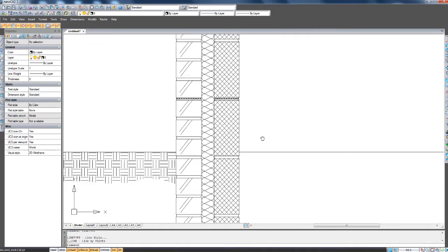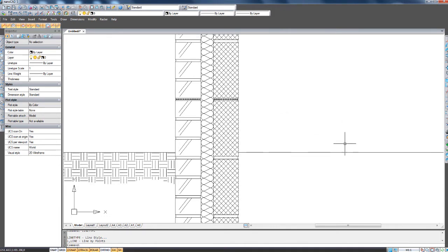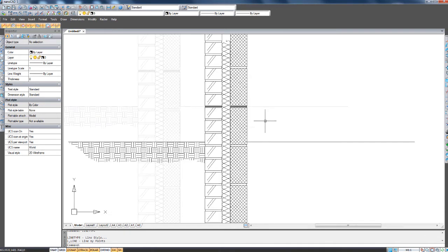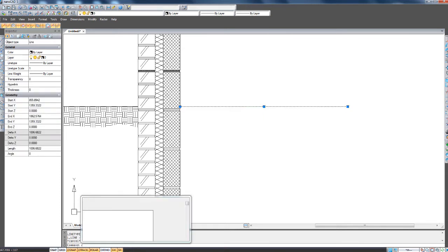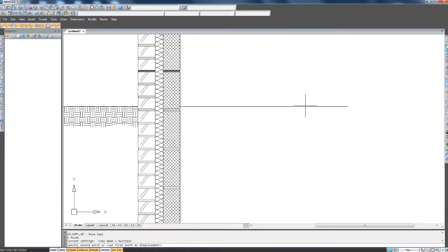If we were going to put a suspended floor in here where air can get in, we wouldn't want water to get in and go down onto the floor and flood the place. So we're making the ground higher than the outside ground, so that can help to prevent it. The thickness of the hardcore layer is gonna be 150 mil. So I can copy this down. Move it down by 150 mil.